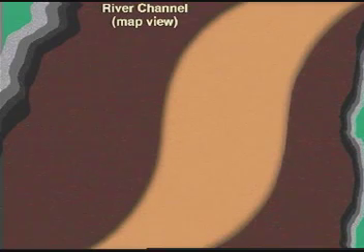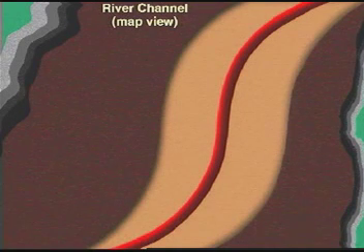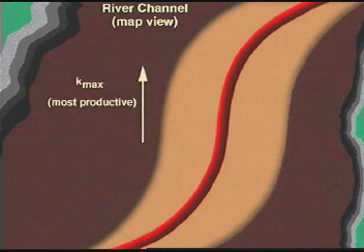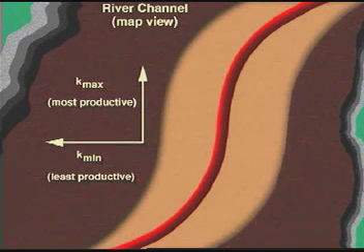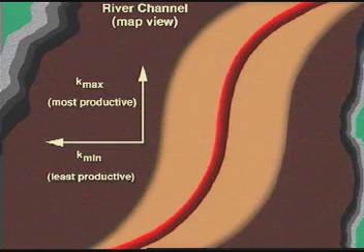In the case of this river channel, our first instinct might be to drill a single well along its length. But frequently, the permeability along the channel path is several times higher than the transverse permeability. A well drilled along the channel path thus exhibits less than optimal productivity.